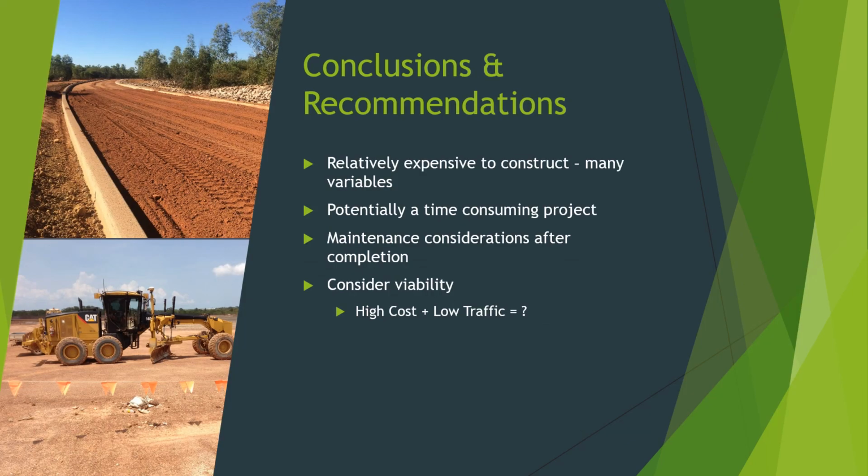Now, just to touch on the conclusions and recommendations following this assessment, it's going to be quite an expensive project with between the ripping of the rock and also the construction of the embankment in relatively challenging conditions. However, time should be saved using the wet mix soil mixing application, which will limit the amount of spoil that has to leave site as well.